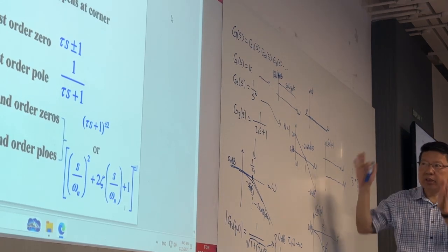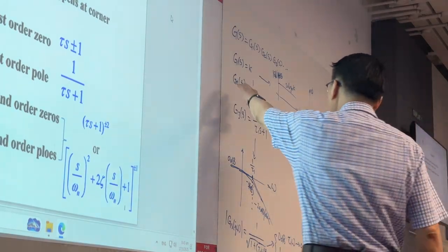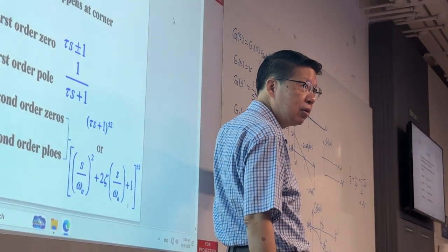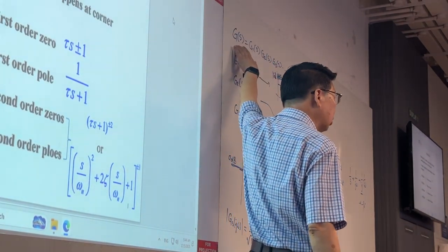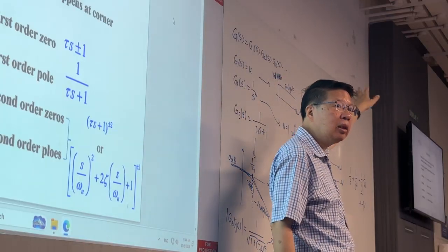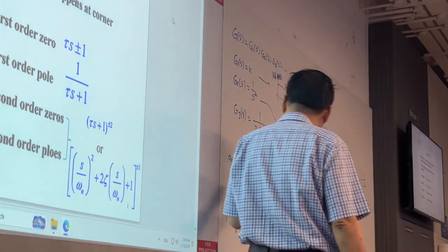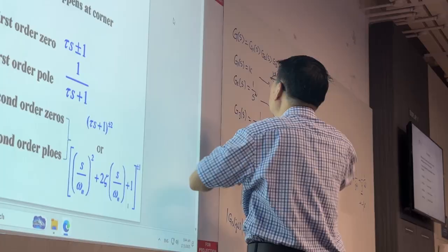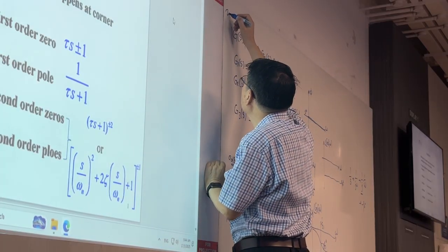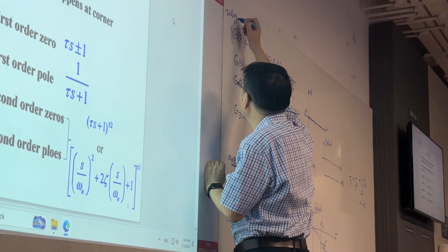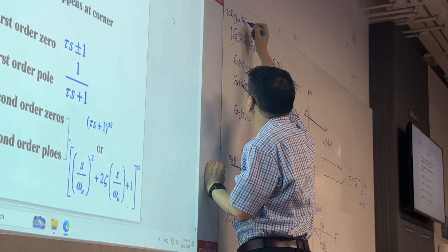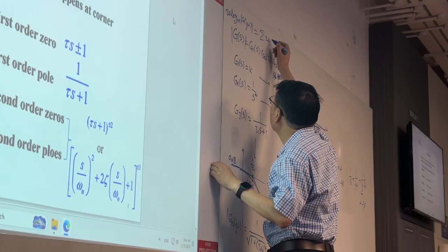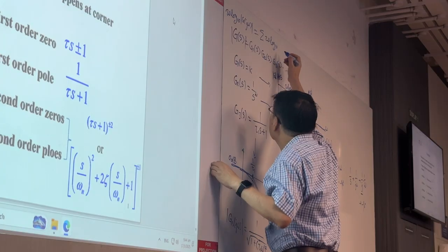Okay. So what we are saying is, for the basic factors, we have the standard Bode plot. Now when we have a complex transfer function, which is a product of many of such factors, and we want to get the overall Bode plot, we will take 20 log base 10 of this, which will be equal to the sum of 20 log base 10 of each.